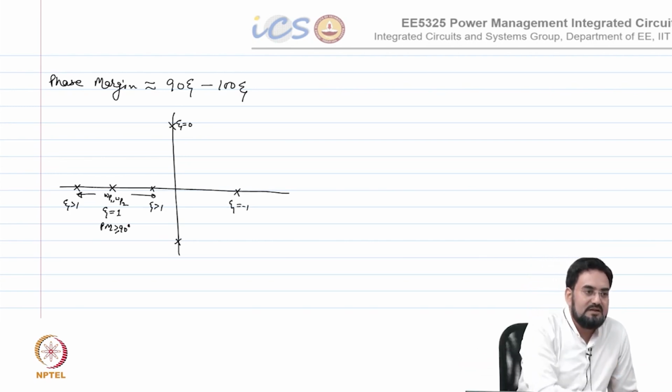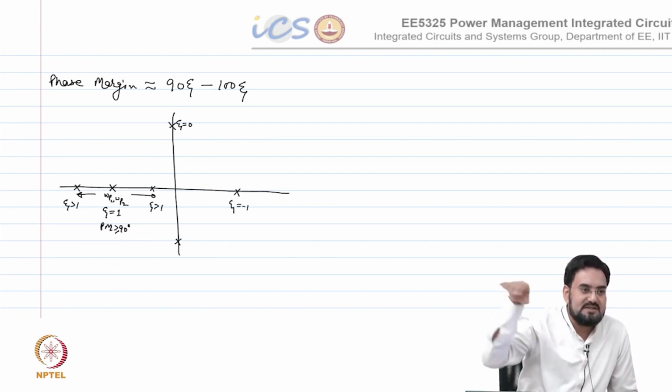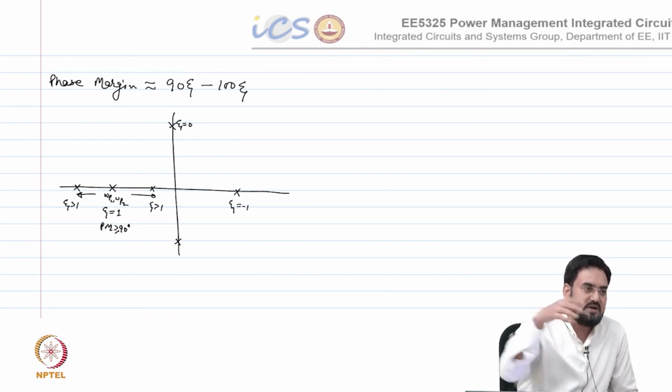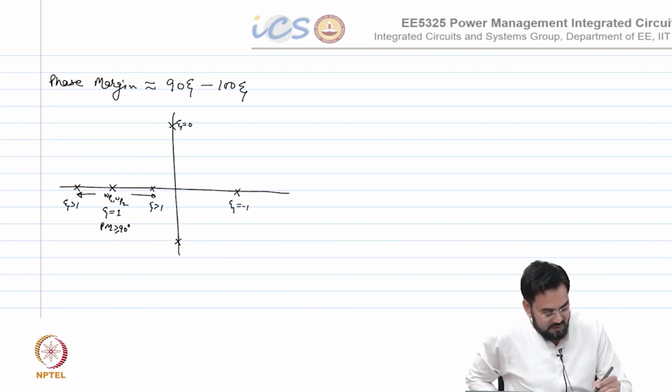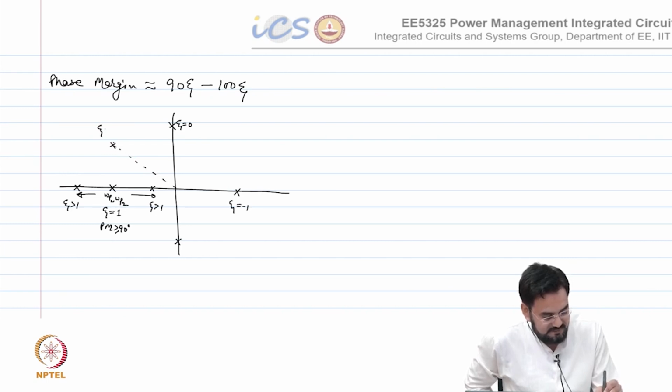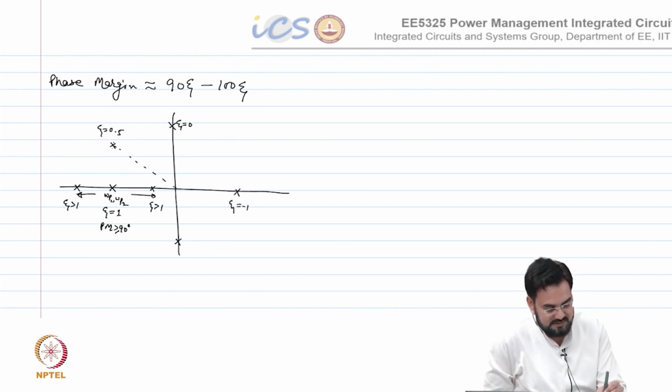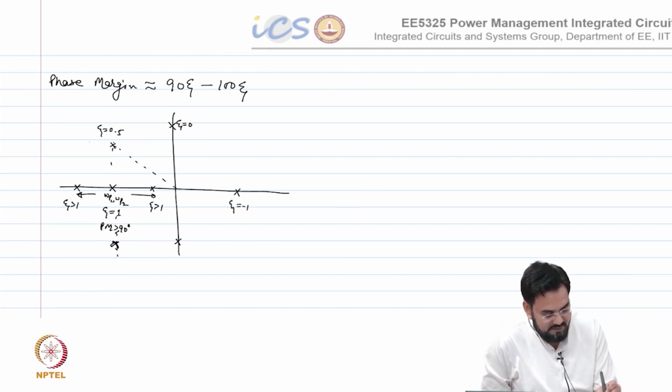then your pole will be on real axis and you won't have any oscillations, because in order to have the oscillations your pole should be on j omega, basically your pole should be complex, otherwise you won't get sinusoid term. And we know zeta 0.5 was somewhere here. Okay. And second pole will be here. So, omega p1, omega p2.